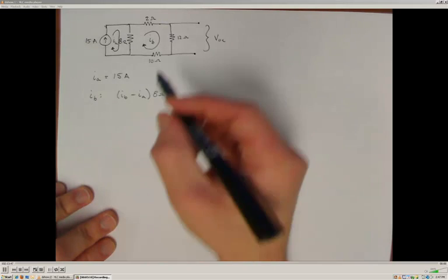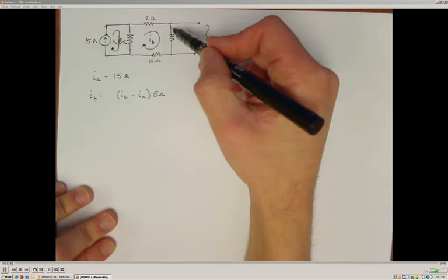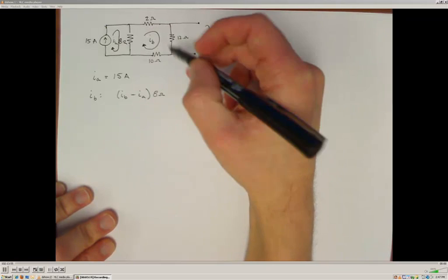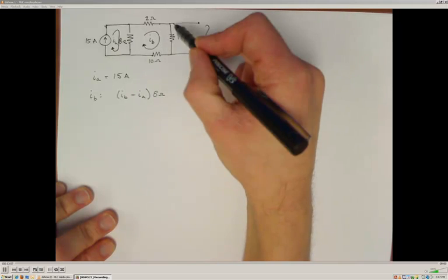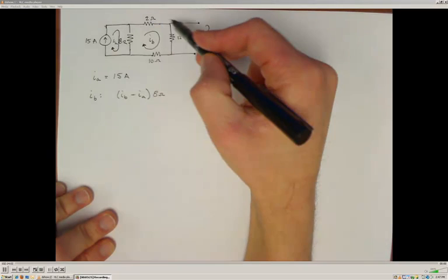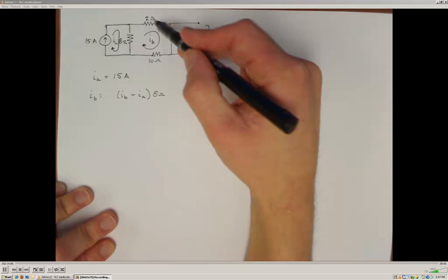Now I need to know the potential developed across the 2 ohm, the 12 ohm, and the 10 ohm resistor, and I know that the same current flows through all of those. Also, based on my schematic, I know that that current does not interact with any other mesh currents anywhere else in those three resistors.